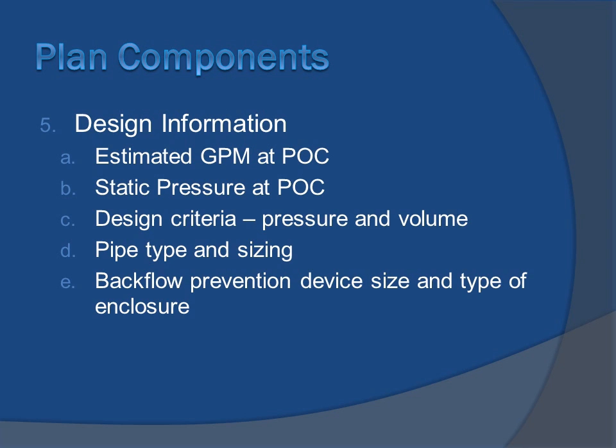Backflow prevention device, the size and type of the enclosure. It used to be above ground. Years ago it could be all underground. Now they're going back to underground. I think they need to be underground. That's the safest place. It's warmer underground than it is sitting above with that little foam box over it. And then the power goes out and the heat tape that's wrapped around it. You got a nasty mess if that thing cracks.